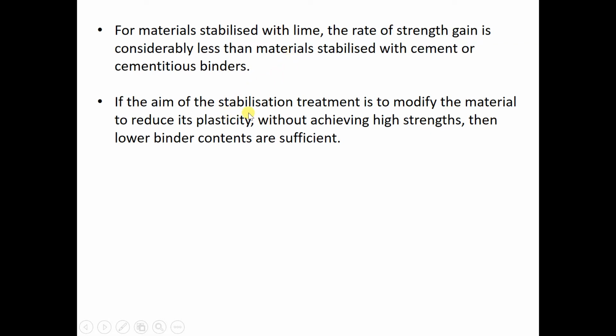Okay, if the aim of the stabilization treatment is to modify the materials to reduce plasticity, for example of clay materials, then probably you don't need a high strength, maybe just a bit of strength increase, but not a very big increase.